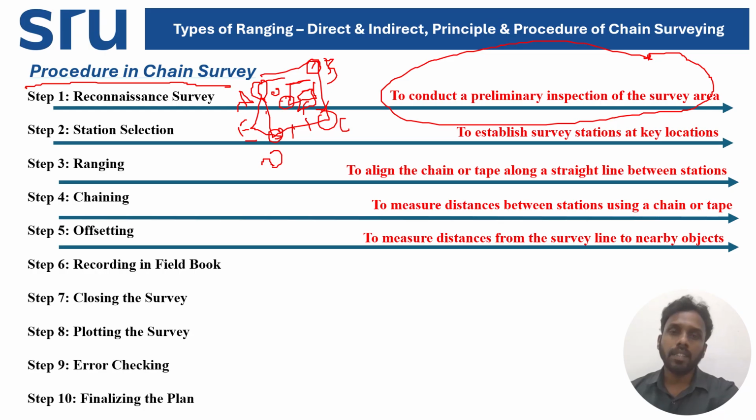Then we measure every detail, because this is very important before doing your planning. If you are not visiting your site, you start planning everything, you spend a lot of days of work on it, you clarify and make your client satisfied, and once you go straight to the site, your site may not be exactly rectangular; it may be a parallelogram.